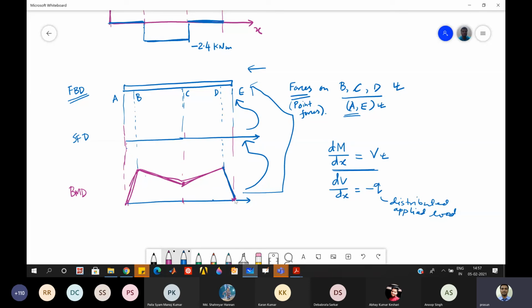And what is the slope? Negative. Yeah, the slope is negative. And if you know the distance and the value here, then you can find out the slope by taking this height divided by the x position between these 2 points. Because the slope is negative, the shear force will be negative, and it will be constant because the slope is constant throughout. Then that means this is the shear force diagram.